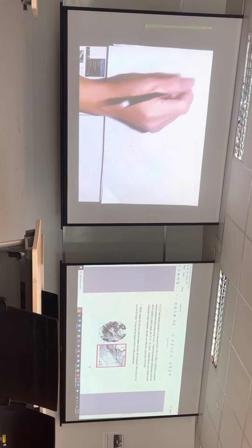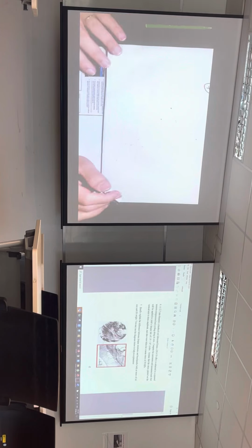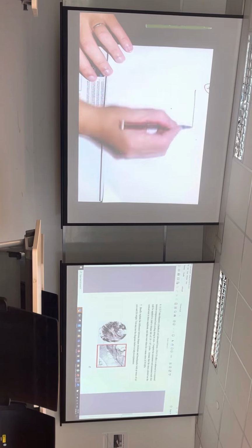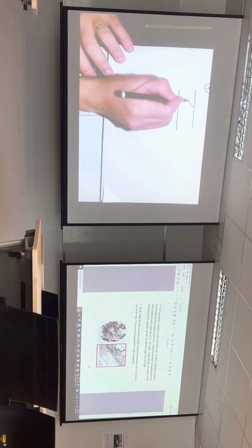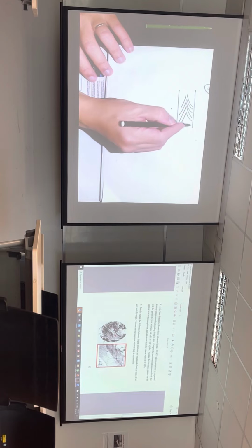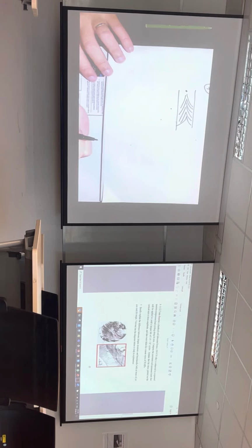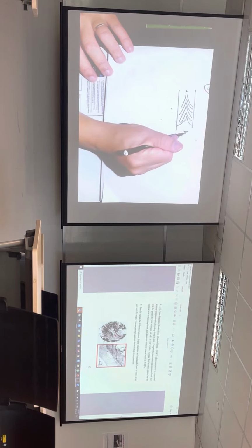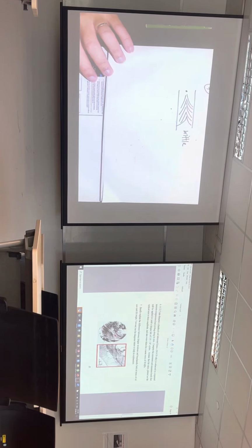Number 7. At this point, I just want to clarify something. I hope you remember when I talk about brittle fracture. Brittle fracture has this funny kind of, if you are the CSI person, it has this idea that it always points towards the origin, something like this, like a chevron. So this will be the source. So for a brittle fracture it always looks like this. Brittle fracture points back to the source.